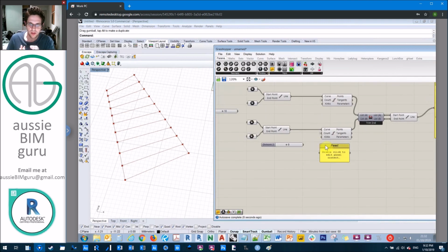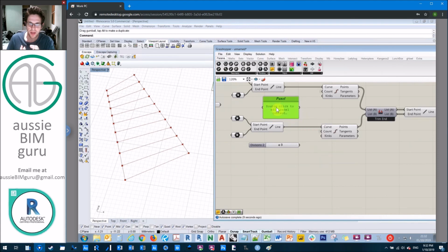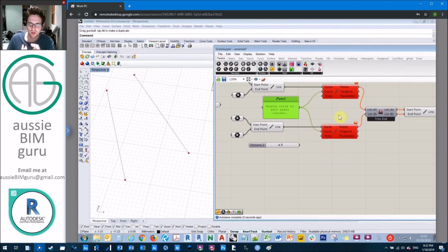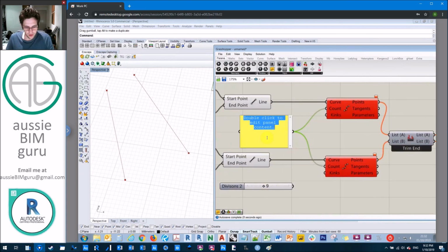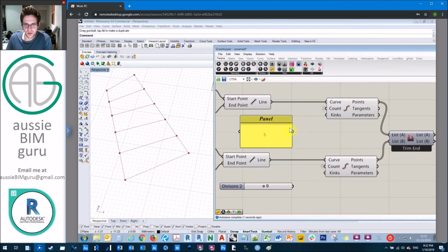Panels can also be used for holding data or values. So instead of having this slider, let's connect up a panel instead. And you'll see by default, it's giving me a red node. A red node means that something is not working and needs to be addressed. You can see here that I can't convert text to an integer. But what I can do, I believe I should be able to put in a number. There we go, I put in 5. And you'll see now this can behave as an input as well. So that can be a really helpful input method.